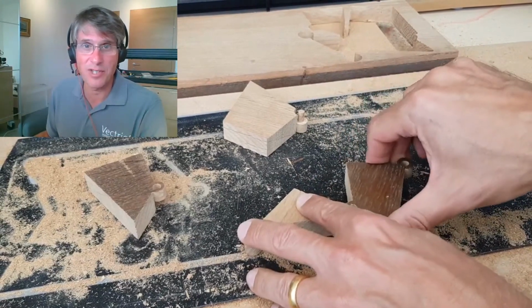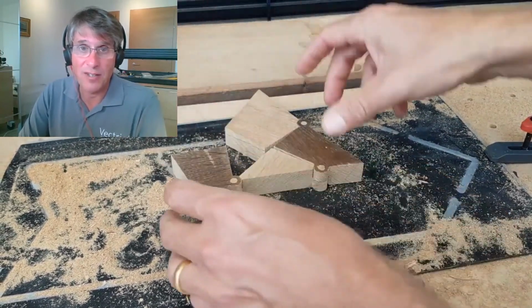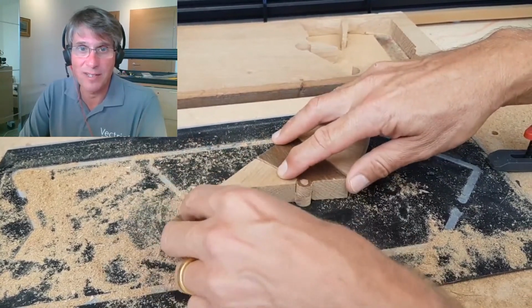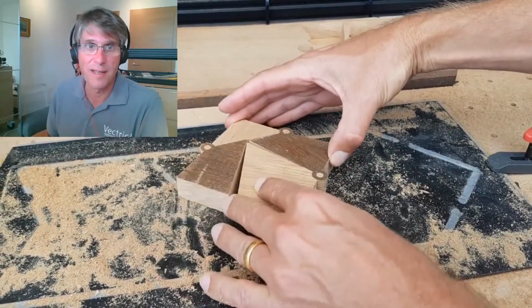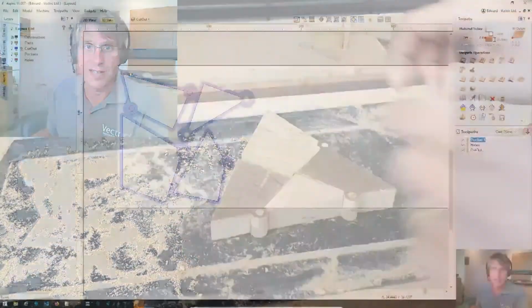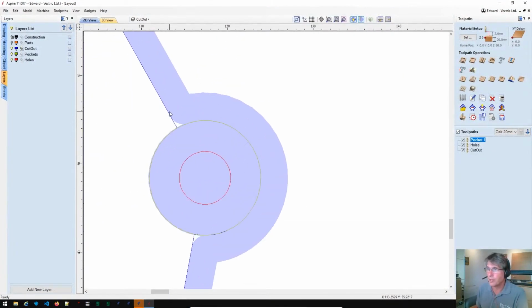And unfortunately, even though this is pretty much filmed straight off the bed of the machine, as you can see, everything fits together. The fit of the joints is fine, but it's a little bit springy, and that springiness, which is preventing them all coming together nicely, is to do with the little fillets in the corners of each of those hinges. So what do I mean by that? Well, really what I'm saying is that here, when we did the cutout pass, what I didn't do was allow a little bit of overcut to clear this sharp corner. And that means that you're pressing the shapes into a space which has got this little filleted radius in there, 1/8 rad.